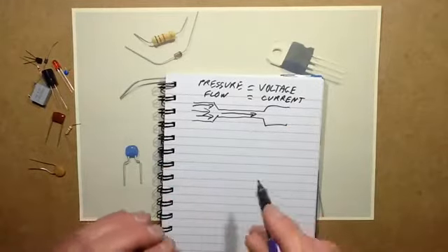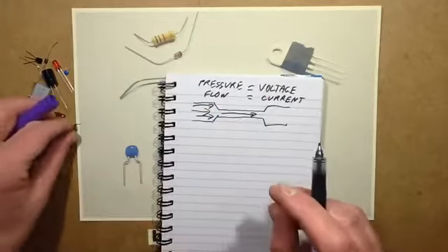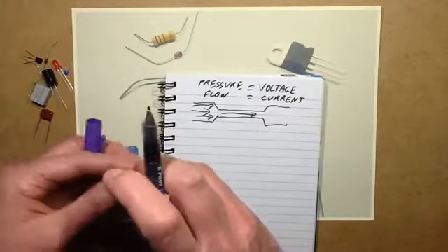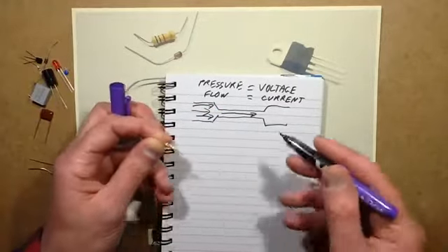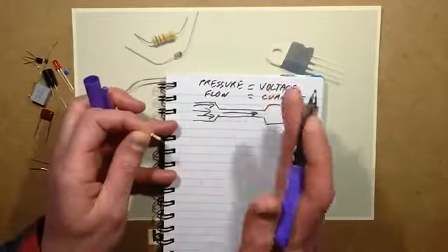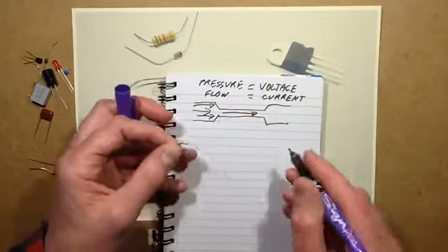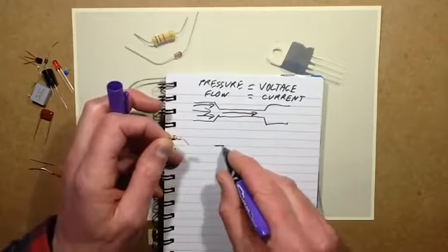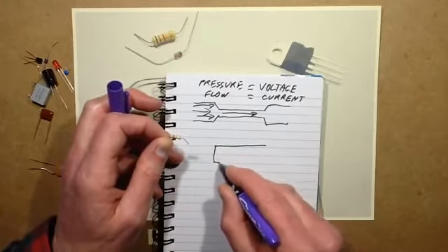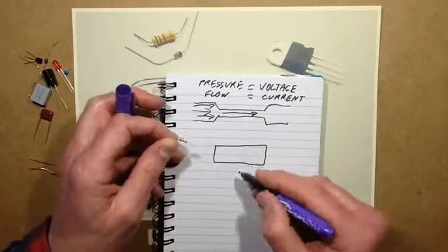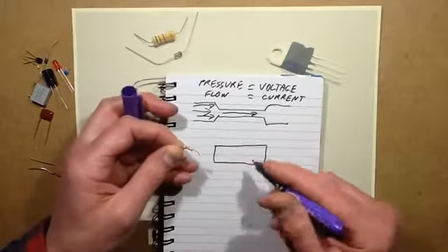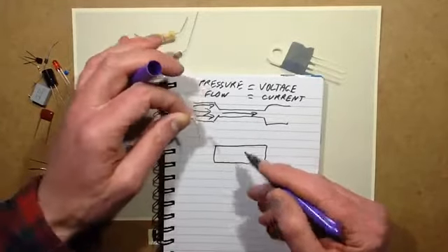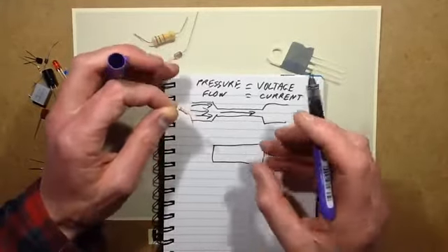Now the construction of a resistor is usually, in the case of these ones, this is a carbon film resistor. And you get metal film, carbon film, wire wound, but one of the most common is just carbon film or the metal film. And they have a little ceramic tube which is coated with either the metallized coating or a carbon coating up to a specific thickness.